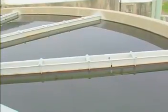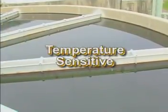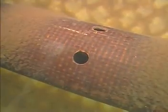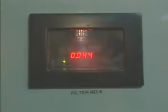Upflow clarifiers use a sludge blanket to trap particulate matter as the water passes through this blanket. These clarifiers are temperature sensitive and require raw water that has a substantial amount of particulates in order to build the sludge layer. The remainder of the particulate matter after the flocculation process is carried over onto the multimedia filter, where it is removed, allowing the clean water to pass through.